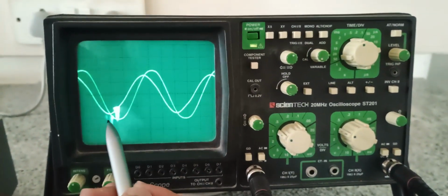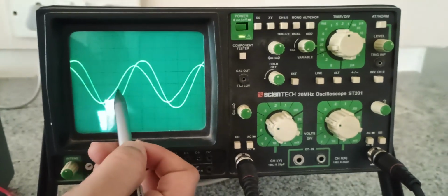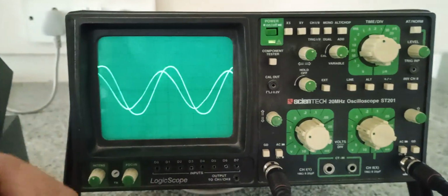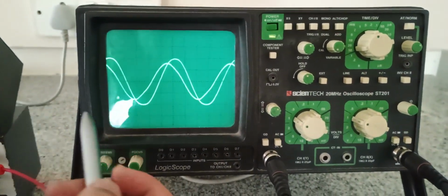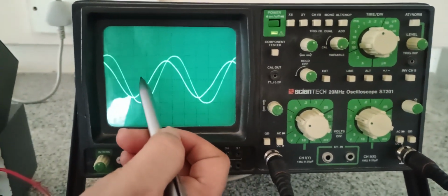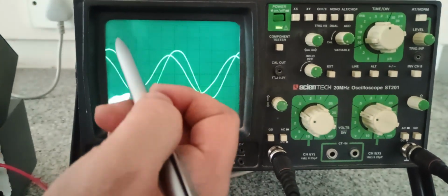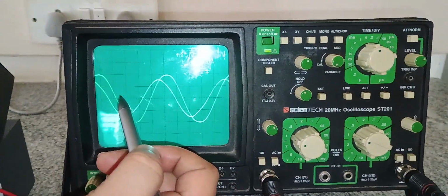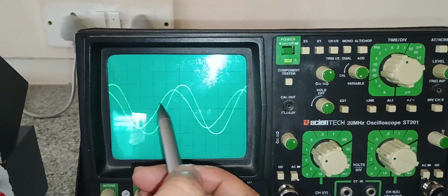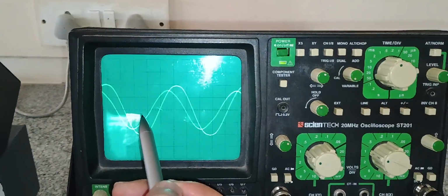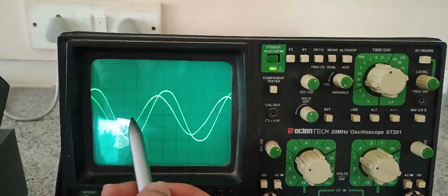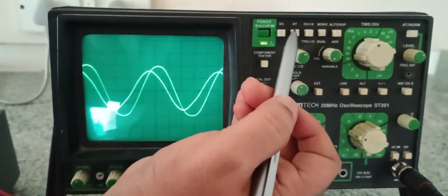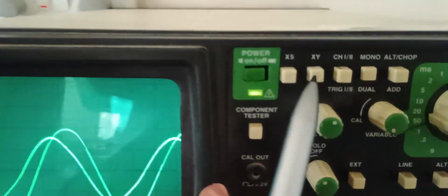Now one more thing we need to calculate, we need to calculate the phase angle difference between the output and the input. That is nothing but the phi value. As we already know, phi is calculated by using the Lissajous circle. The Lissajous circle is nothing but the combination of x and y components of input and output. So you need to mix the x component of input and y component of output. That is called the Lissajous circle. Sir, how to get the Lissajous circle?